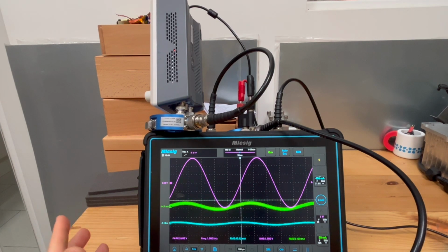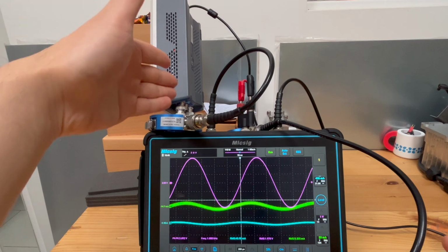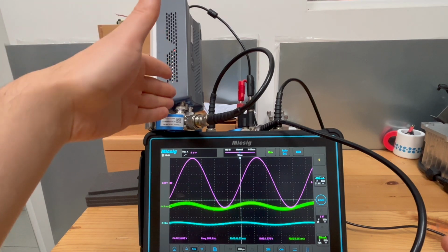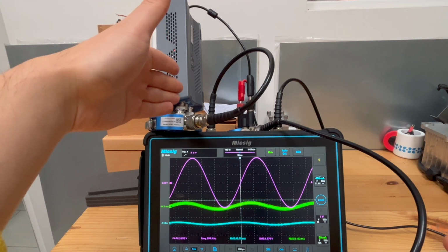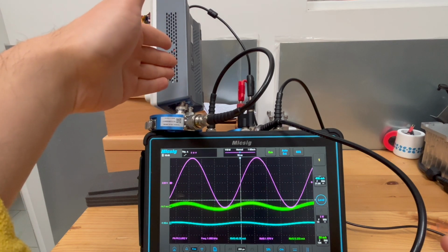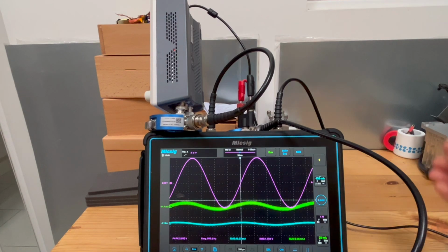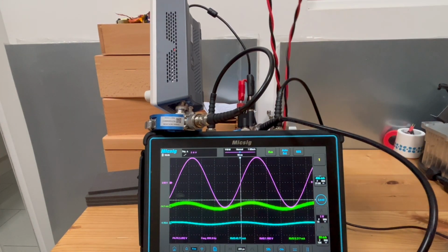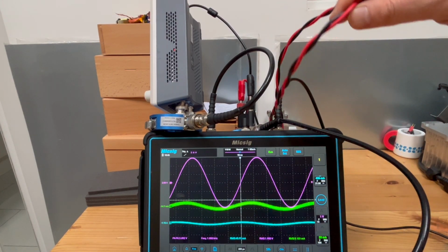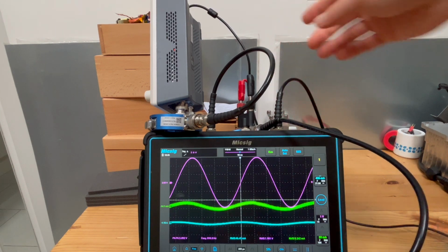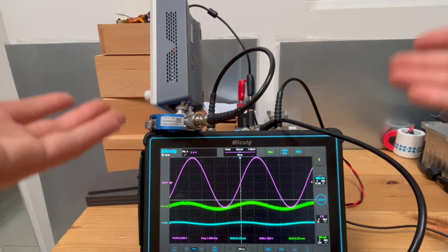And we have two return paths really. One is a short, broad connection, serving here as a BNC connection, right? And that is a short connection. And we have a longer, thinner return wire, which is part of this coaxial cable, the black wire. And we monitor both this time, right?